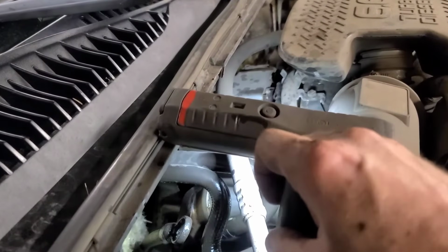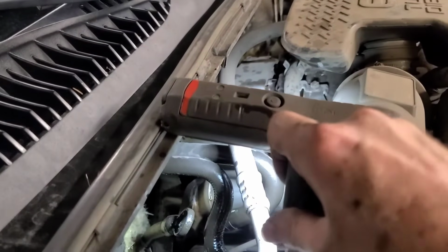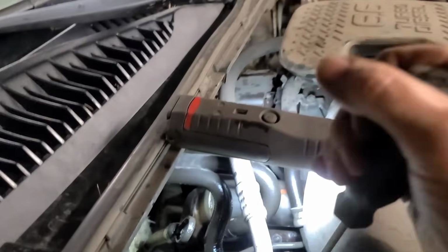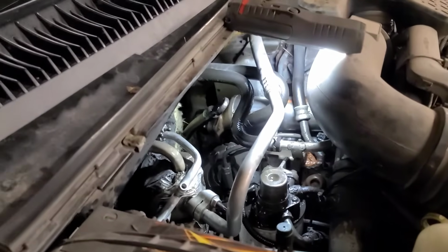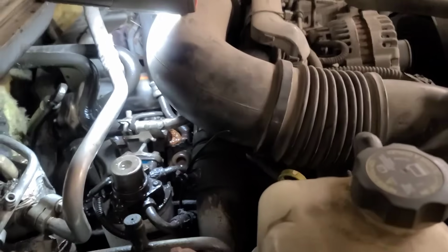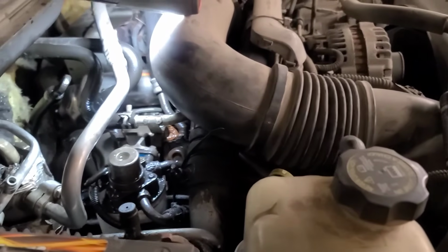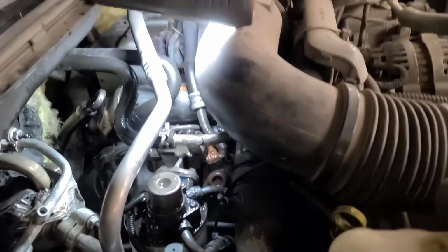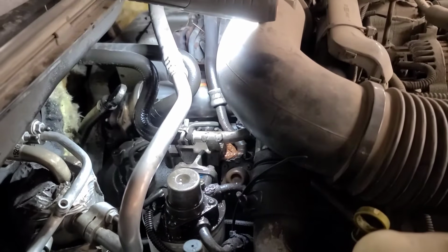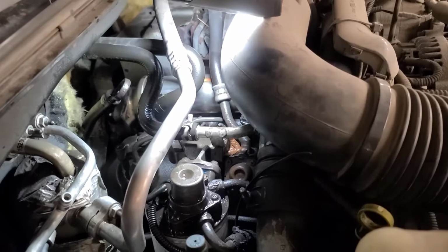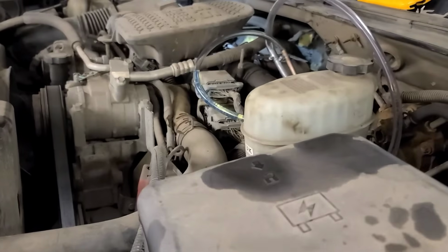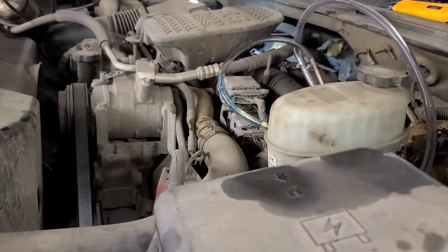Trouble is, I don't have a helper here to start this vehicle and watch for air bubbles underneath. But I'm sure it's not leaking anywhere along the line. It's got to be leaking in the pickup or at the pickup in the tank. I hate like hell to drop that fuel tank because it's 3/4 full. Oh well, I'm going to get a helper.